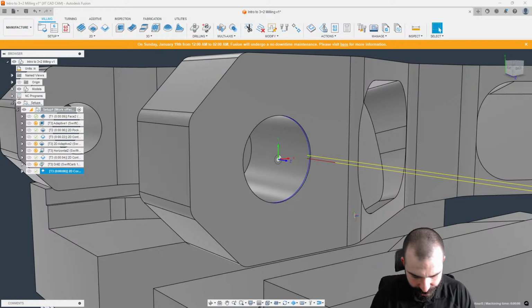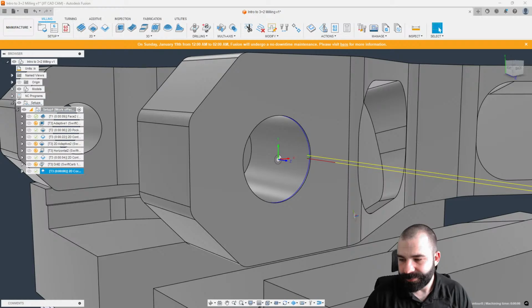Okay, so you have an O-ring groove in there. And then let me scroll up to your question. So your question was, used a boring bar as an end mill so that I can cut an undercut, but it wouldn't let me profile a radius. Okay. So did you model that or try to use that as a T-slot cutter? Because I assume you're saying you put a boring bar in your machine and spun it like an end mill, correct?